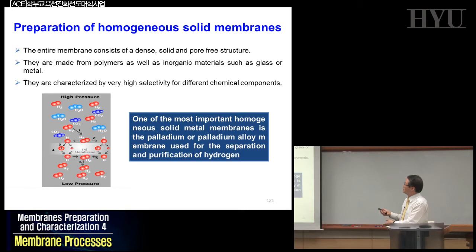And next, the topic that we have already talked about is the palladium membrane. Okay, palladium membrane could be classified as ITM, ion transporting membrane, because through this palladium membrane, which is a metallic membrane, hydrogen molecules cannot penetrate through, but the only mechanism of this hydrogen separation is through this ion transporting mechanism.